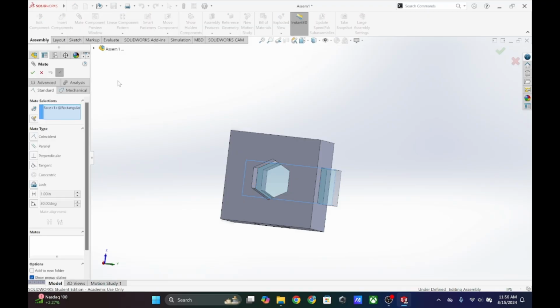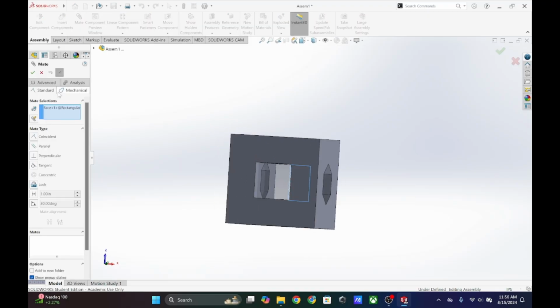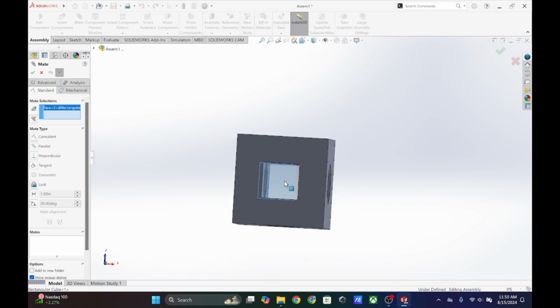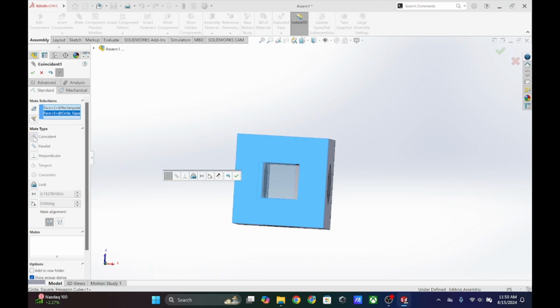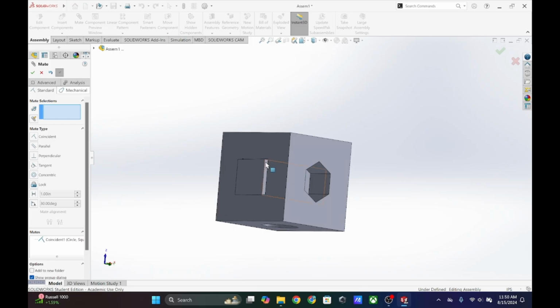And so we can manually align it, kind of best to our ability, but there are features within the assembly called mates. And so with a mate, what we are going to do is, go ahead and delete that. We are going to mate this face, the flat one, with this side here. And this is going to be a coincident mate. It's like this. And so if we create it, now we see we can move a rectangle around, but it stays attached to that face.